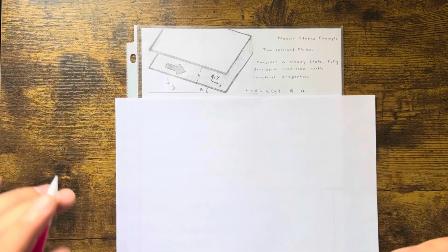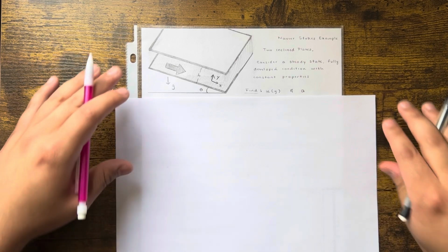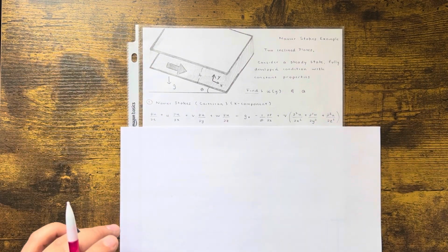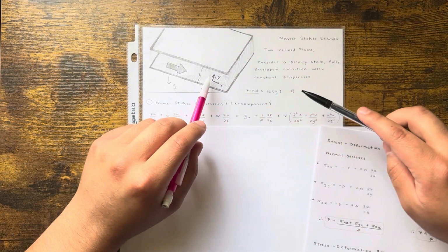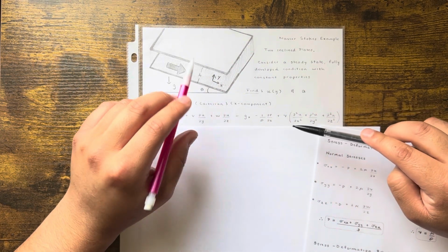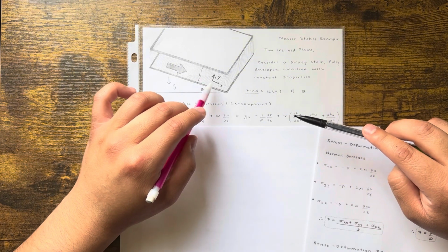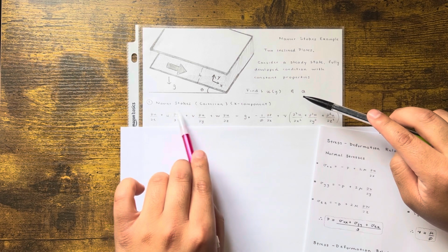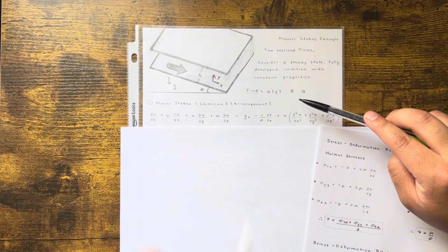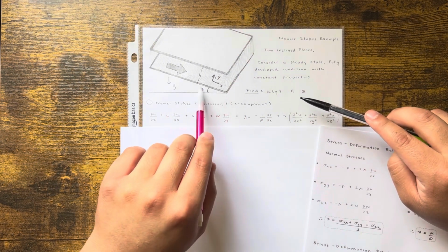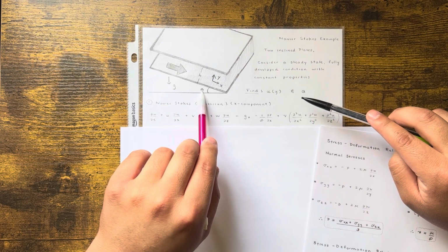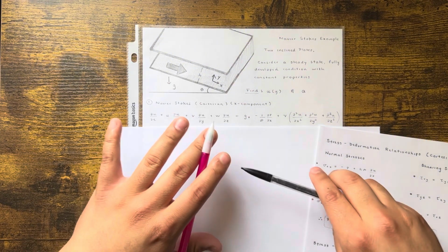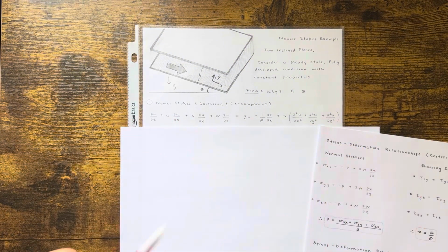If you've been following the other videos, you'll know that we always start off with the Navier Stokes equation. I tilted my axis. It's better to tilt it, as I explained in the previous video, because if you were to have the normal x and y, you'd have to use both the x and y components of the Navier Stokes equations. If you tilt it, the only thing that changes is you have to deal with a theta version of the g. You'll see what I mean in a second, but it's better to tilt it now, and then you just deal with the x component.